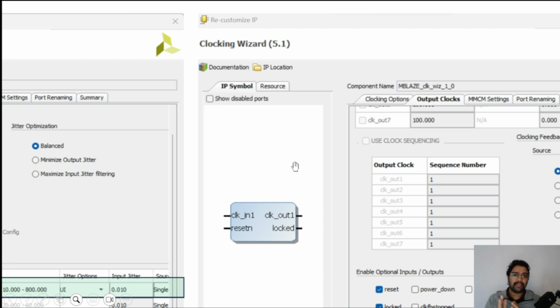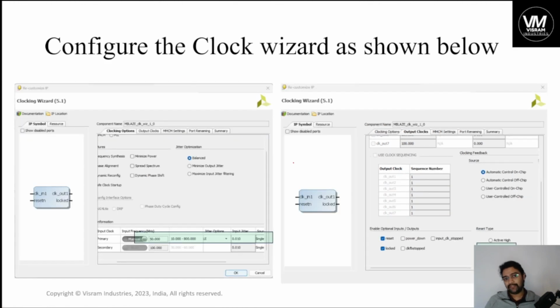So there shouldn't be any slipping of clock pulses, like the introduction of delay due to some other external elements in the processor. Don't get confused too much, I'm just giving a virtual example. So that is the importance of clock. Based on the clock, the entire sequential circuit works, and the major difference between a combinational circuit and a sequential circuit is the clock.